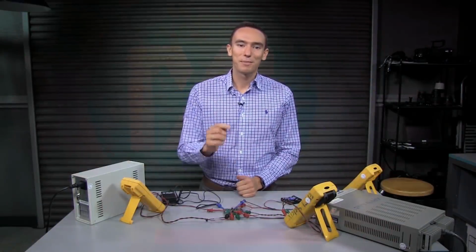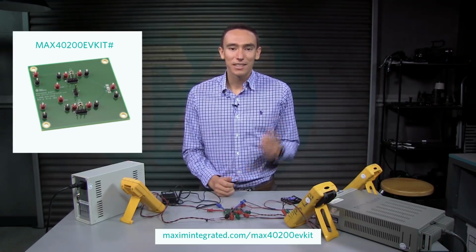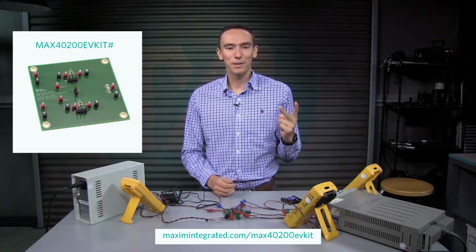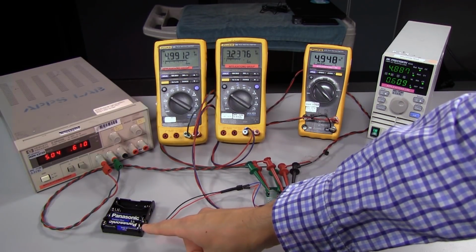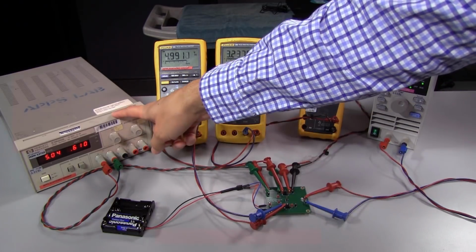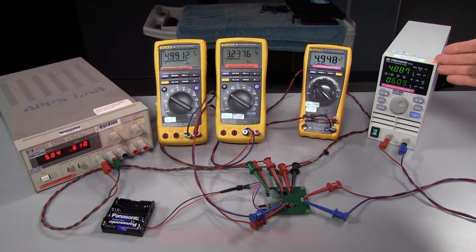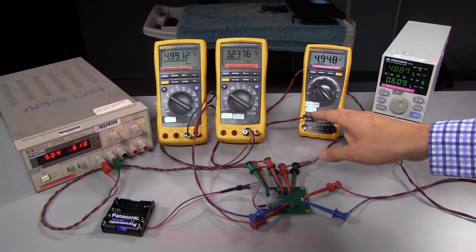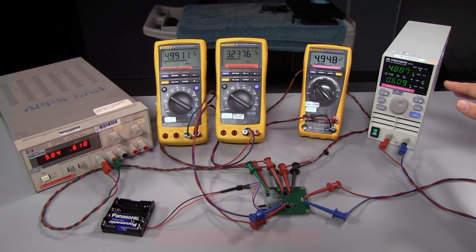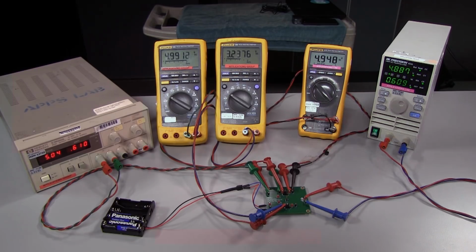For today's demo, I'll be using the MAX40200 evaluation kit. It has two MAX40200 ICs with their outputs connected together to protect two different input sources. The evaluation kit has a layout that's spread out so it's easy to work with, but in an actual design I could really shrink down the size of that circuit. I have two AA batteries generating 3 volts connected to one input, an external 5 volt supply connected to the other input, and an 8 ohm resistive load attached to the output. Here are some multimeters monitoring the two input voltages, the output voltage, and the resistive load current. I'll superimpose these meters onto a circuit diagram so we can look at what's going on.